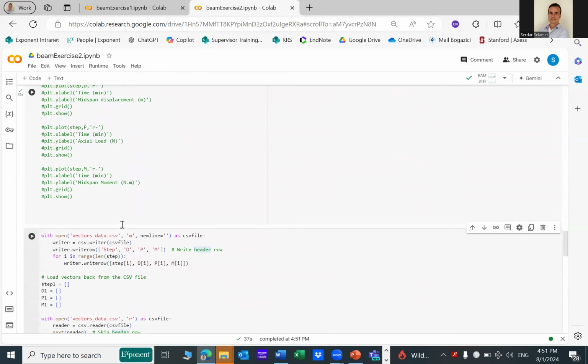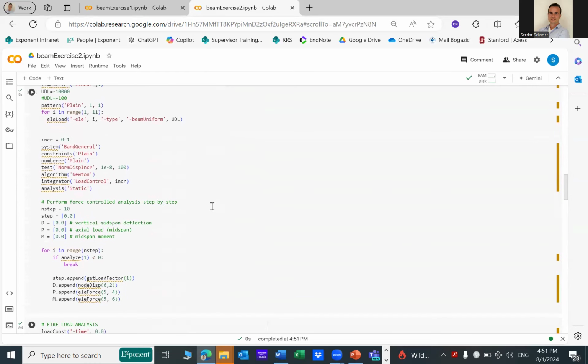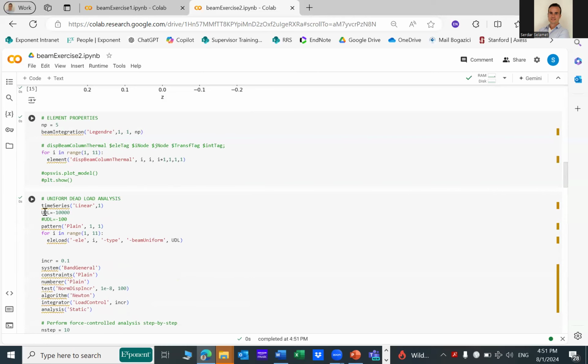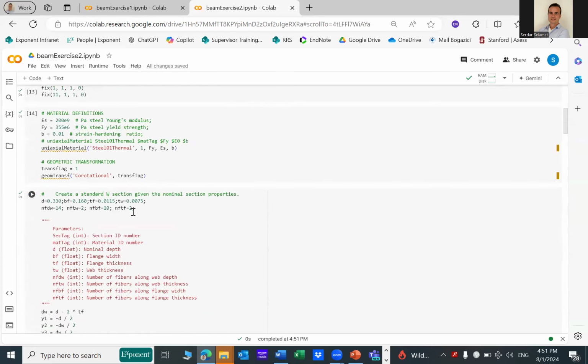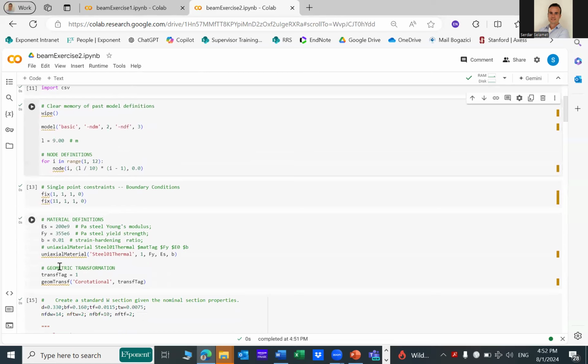all right. Now we're going to save it to a file. Now we're going to go back, and change the loading to only 100 newtons instead of 10,000 newtons or 10 kilonewtons per meter. We are changing it to 0.1 kilonewtons per meter. So we are decreasing the load initially, and observe if there's any changes in the behavior of that beam.